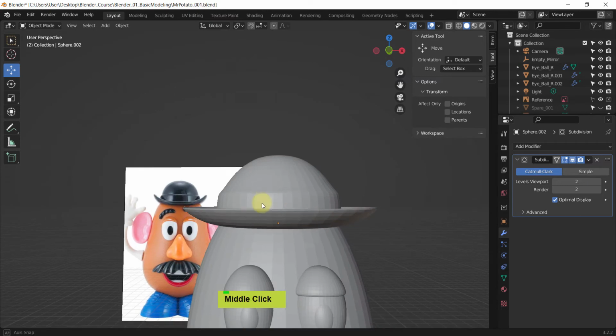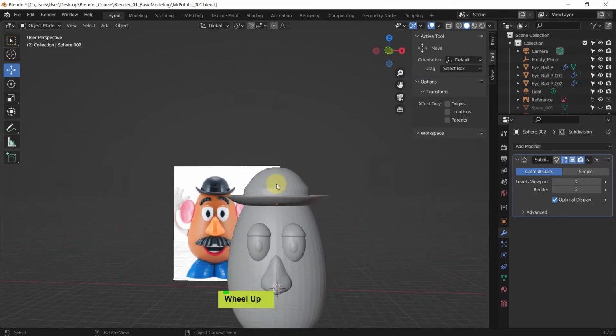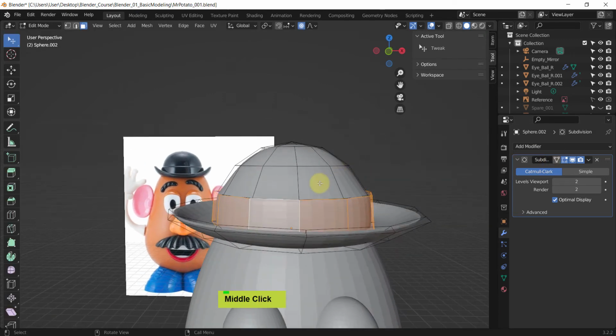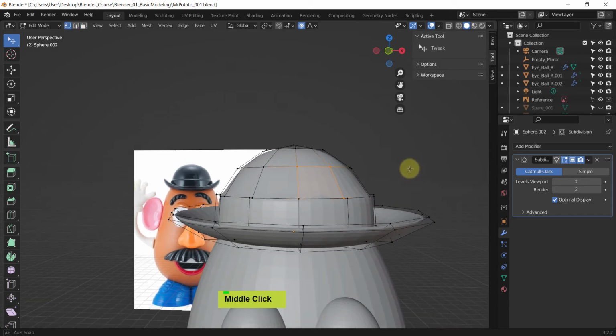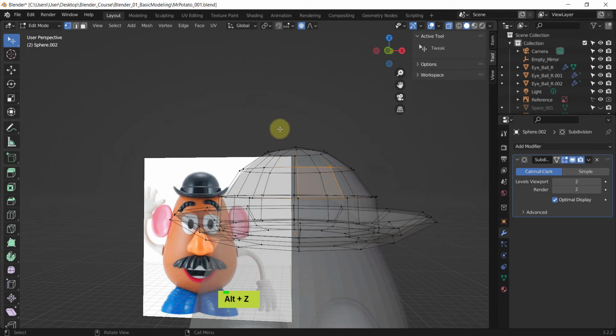Okay, and the roundness is a bit off, so I will lift this up a little bit, correct the points. So edit mode, going in, and vertices, and this area, so Alt Z, and this area, all go to box.